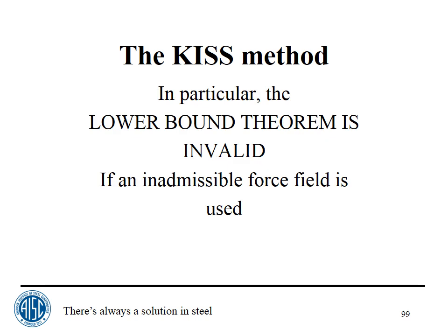In particular, if you don't have an admissible internal force field, the lower bound theorem is not valid. So you're up the creek without a paddle, so to speak. Although I really think down the creek without a paddle is probably worse, because at least up the creek you got the current to take you back down. So you really don't know. You don't know whether it's okay or not. Is it okay? I don't know. But if I satisfy equilibrium, I know that I have the lower bound at my back as long as I satisfy all the limit states.